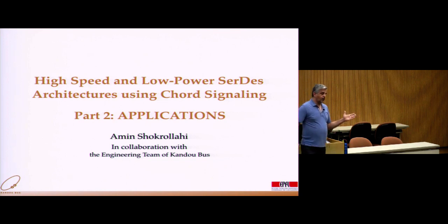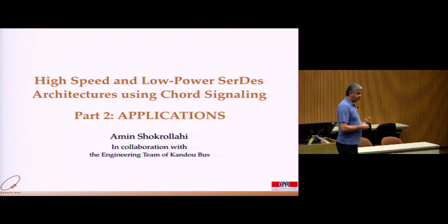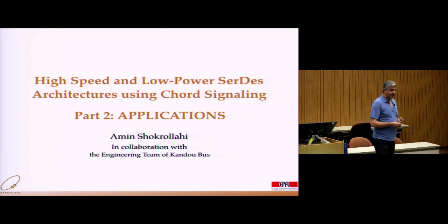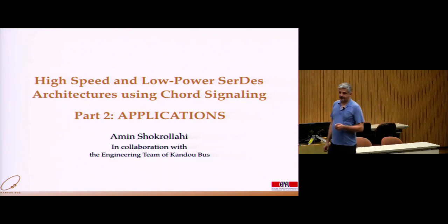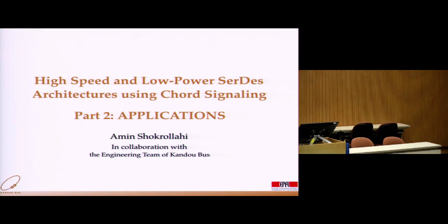Number two is, generally when you use error correcting codes for the kind of noise that you hear, you need to have long codes. And long codes mean delay. In chip-to-chip systems, the largest delay you can handle is maybe 1 or 2 nanoseconds. So you have to have really short codes to be able to deal with it. And also, I don't know of any code that can deal with the various types of errors you can see here.